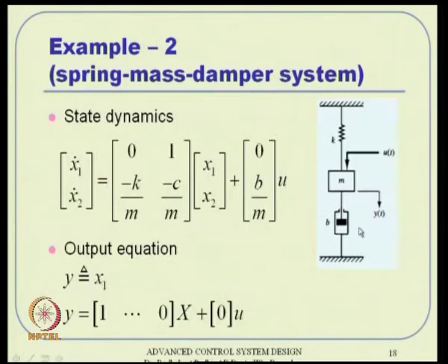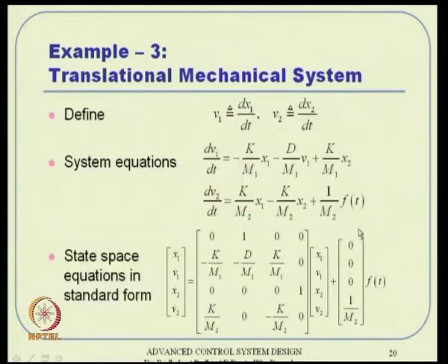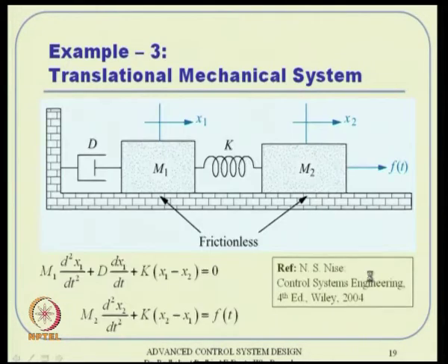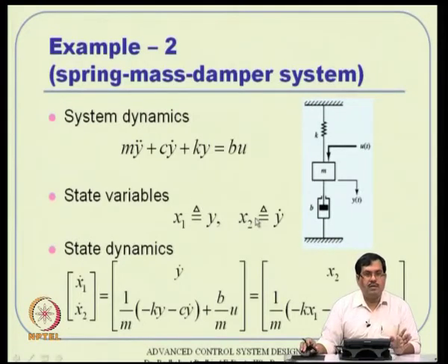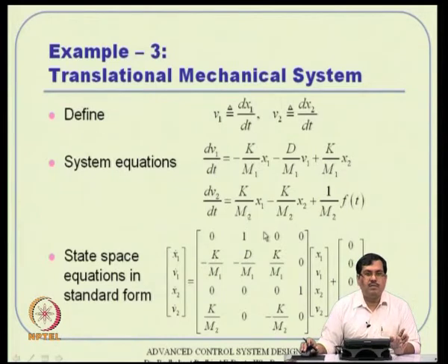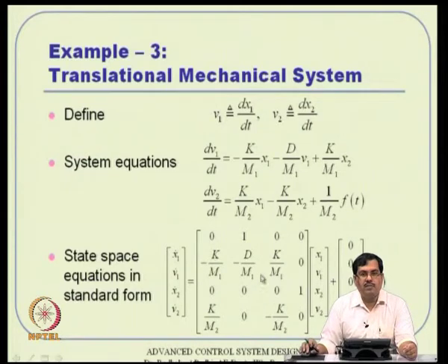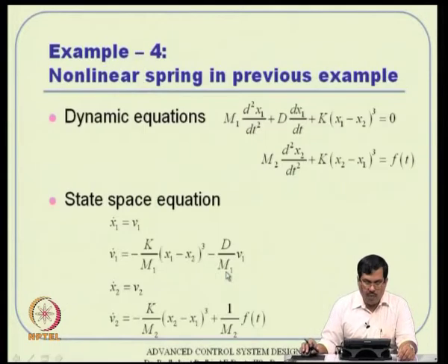Okay. Anyway, coming back to what we are discussing, this is my A matrix, that is my B matrix. So, what you see is starting from a simple linear system. As long as whatever order is there, we will be able to write it in the form of Ax plus Bu, even if they are coupled together, there may not be only one at a time basically. If I see this A B matrix, I am talking about the dynamics of both M1 and M2 together. So, I will be able to analyze the system dynamics in a coupled way basically.